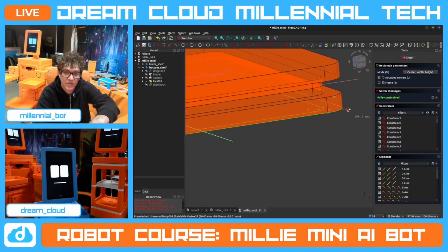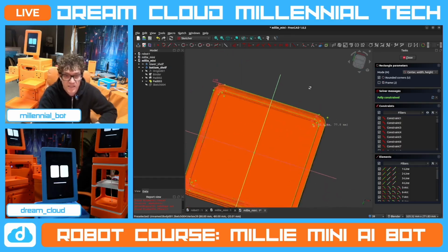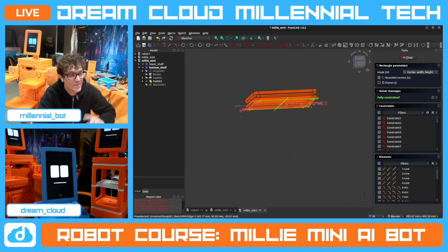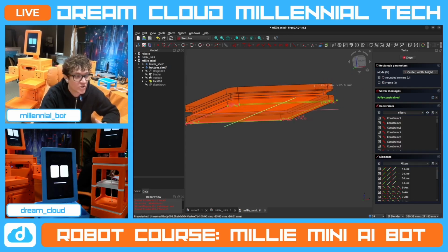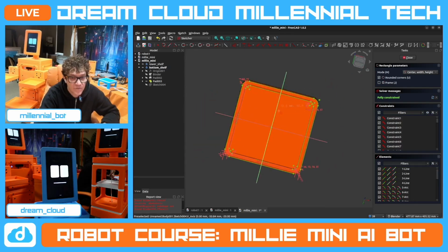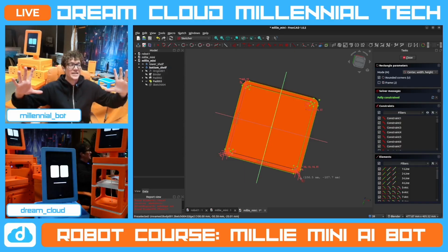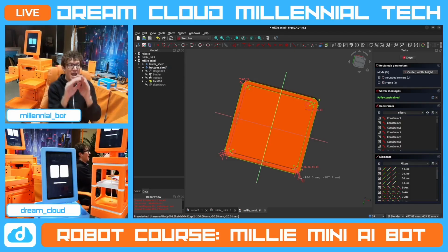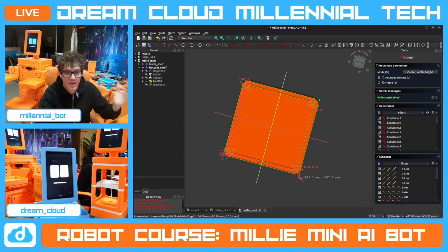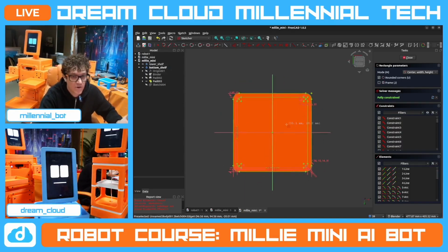We use the same dimensions so they line up, but now we're going to extrude this downwards. So essentially this is going to become a pad, but instead of filling in all of this, it's going to automatically know, because of the software, right? We don't have to tell it. It's going to automatically know that what we actually want is this space in between the drawings. So it's going to create a pad out of everything from inside the outer drawing and outside the inner drawing. And it's kind of hard to make sense of that, but that's basically what you need to do, right?